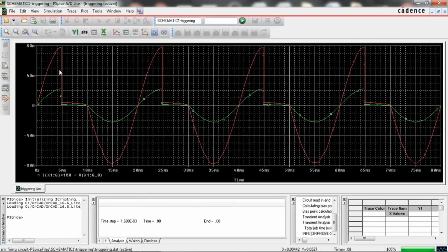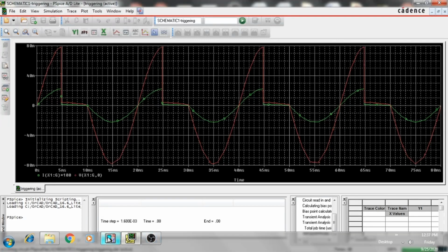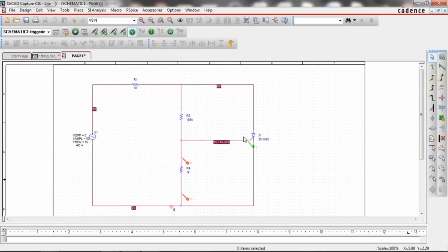See, negative voltages and negative currents. But the problem here is, when I was explaining the SCR, I said when the SCR is in reverse biased condition, in the negative cycle, the anode is more negative than the cathode. At this time, when J1 and J3 are reverse biased, we should not inject any carriers towards the gate, because if you inject, your SCR may break down or get damaged. So remember, when the anode of the SCR is made negative compared to the cathode, we should not inject any carriers to the gate, but this circuit does it.